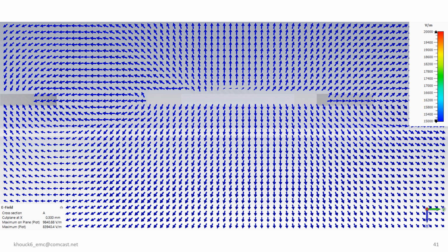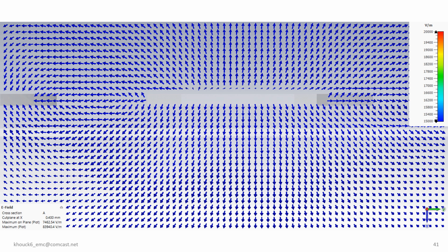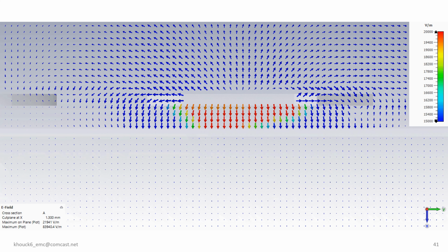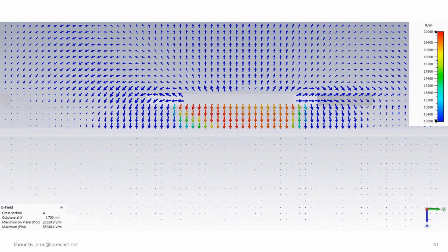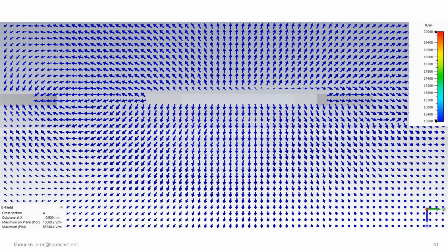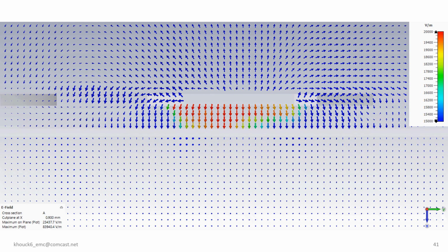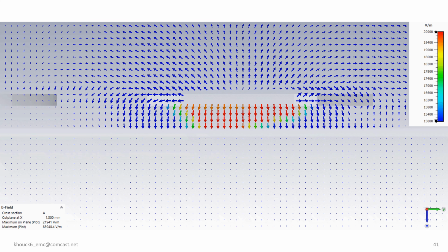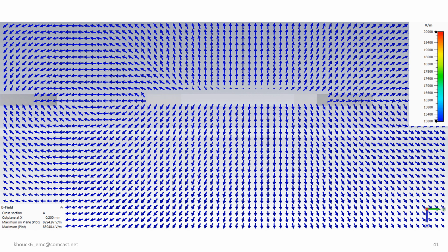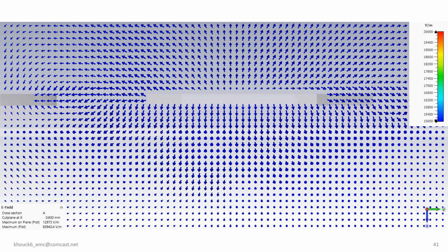Initially, the signal begins with a dominant reference laterally situated between the pads. However, as it progresses, the dominant reference undergoes a transition to the reference plane positioned beneath the trace. To ensure efficient field propagation, it becomes imperative to enhance this reference transition. Fortunately, this enhancement doesn't necessitate complex calculations, but rather relies on a straightforward understanding of applied field behavior. By addressing such reference transitions, engineers can effectively optimize signal integrity and minimize signal distortion in super high-speed PCB designs.